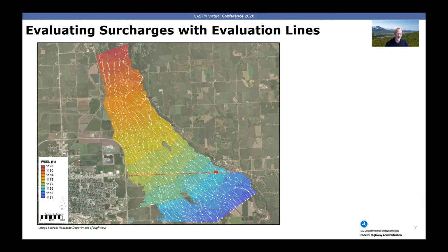An average approach like this is consistent with the current state of the practice. It's what we do in 1D modeling. And the BFE, or base flood elevation, contours are already perpendicular to the flow, and their location then is not subjective. So they seem to provide a good reference, and we've not identified any roadblocks with this approach as of yet. Again, as I mentioned, for this example, I used 2-foot base flood elevation spacing, but for future application, I certainly would refer you to any guidance provided by FEMA when that's released in November regarding appropriate evaluation line spacing.